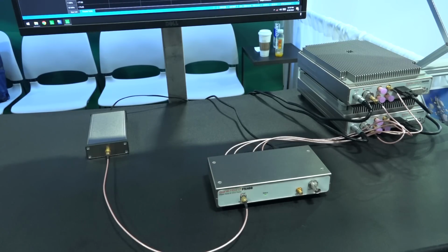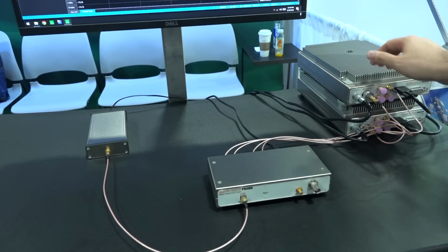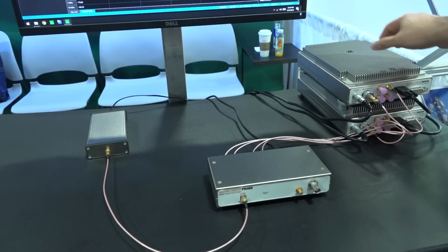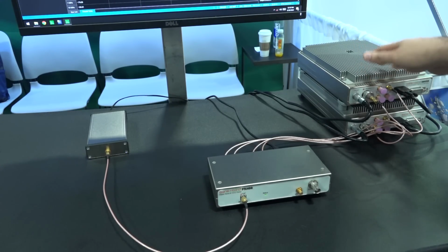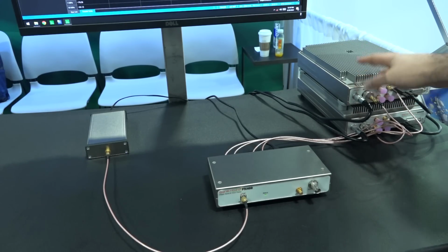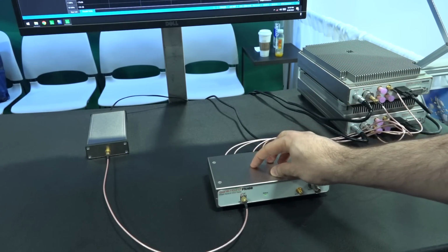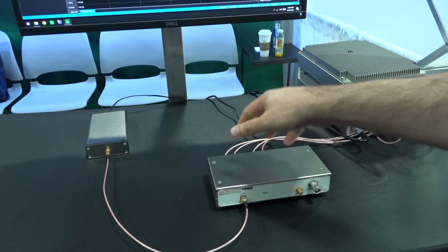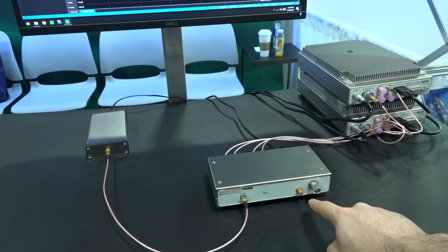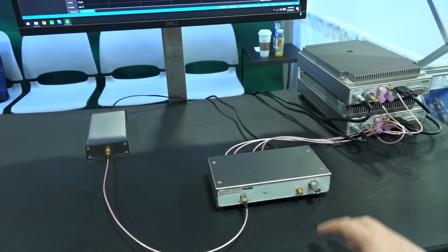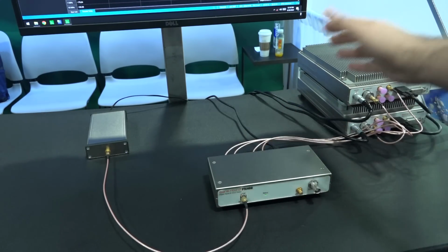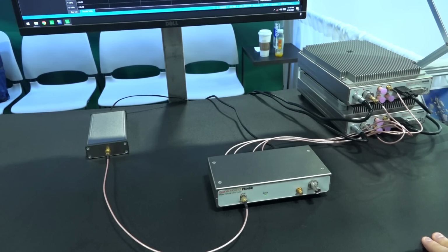And here at Siglent Hound, we actually now have a signal source analyzer set up using their broadband SM435 real-time spectrum analyzers. So the idea is fundamentally quite simple. If you have two of these spectrum analyzers, you can connect it to this new box, the PN400, which has the gating as well as the signal splitting built into it, and it also has the low noise voltage sources, so for VCO characterization. So this becomes the front end of a cross correlator for phase noise analysis, and the signal then directly goes into two of your spectrum analyzers.